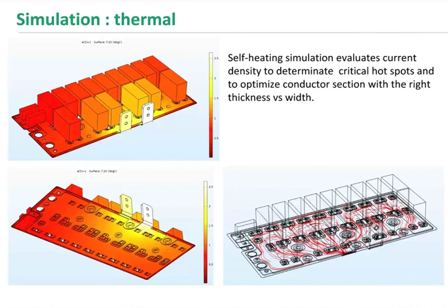And you see on the right picture that there is a density of the current flowing through the busbars. Here, in addition, to make sure that the terminals can handle the requested current, we changed the thickness of these terminals by adding a smaller busbar, which was welded to these terminals, as all this DC current is running only through these two terminals.